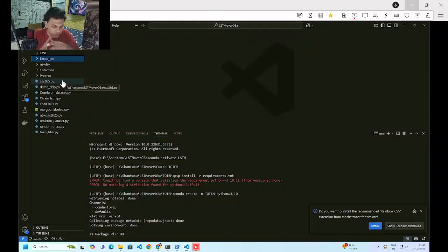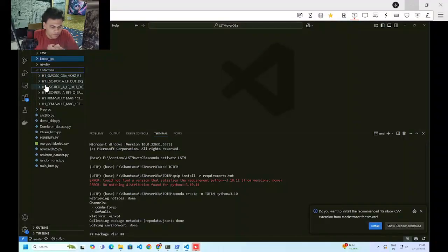We have obtained the data for the strain channel of the O3A run for 96 consecutive time segments, and we have also obtained data for 5 other auxiliary channels. 2 of them were at a sampling rate of 4 kilohertz, and the other 3 were at a sampling rate of 2 kilohertz. And this sampling rate is decided by the nature of the sensor, not by any intermediate processing part.